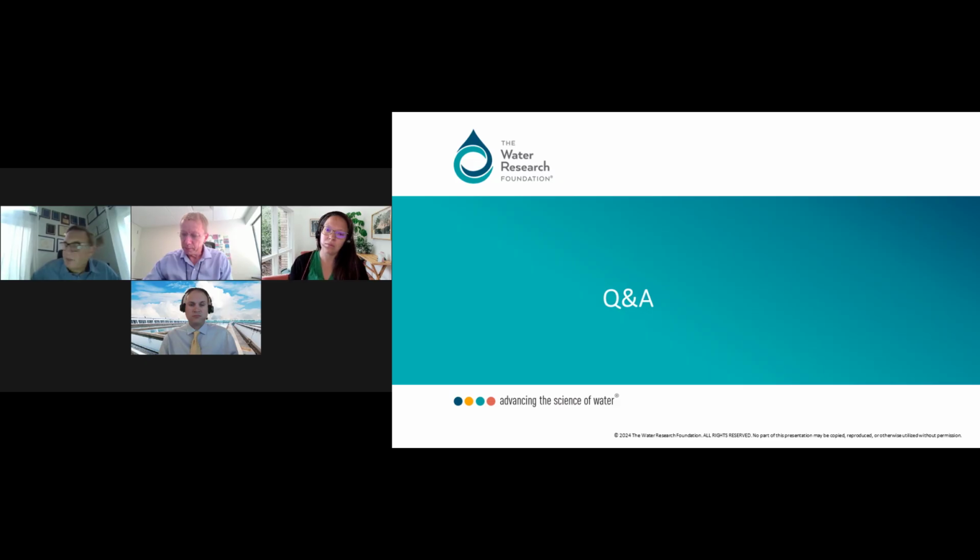I can probably answer that question because I investigated it in detail. So there are a couple of issues. First of all, based on the experience of the industry, placing it up front, especially in primary effluent, the sensor is prone to biofouling. And this is issue number one. Secondly, we tried it and we did not see significant benefits for control, but drastically increased requirements for maintenance, and the plant staff was not happy with it.